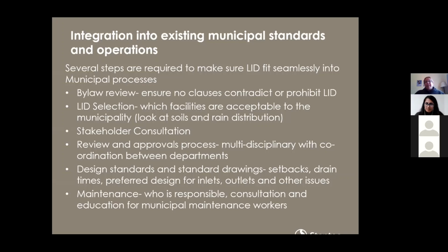You're going to need to consider what your drivers are. Your drivers might include water quality, nutrient removal. It might be volume capture or a stream health metric. How we design the LIDs or how we set up the program will depend on what those drivers are.